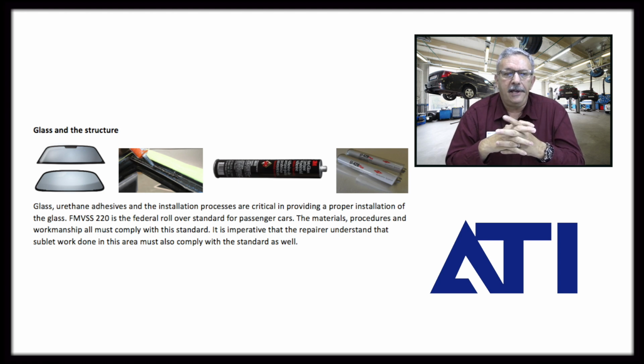In an effort to cycle the vehicle quickly through the repair process, we've got people that are coming out with all of these quick cure adhesives. We need to know that that adhesive will withstand the requirements of FMVSS 220. If it doesn't, they shouldn't be using it.